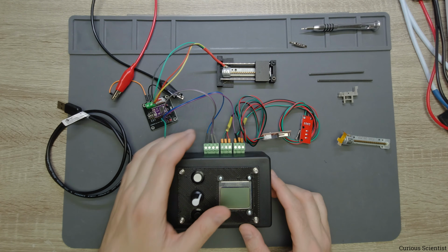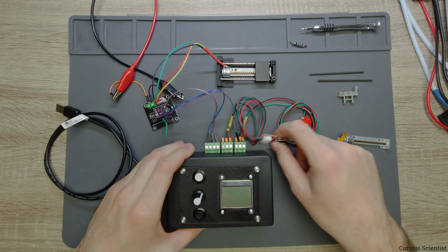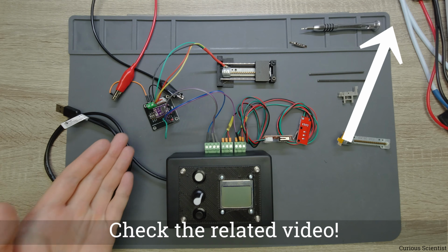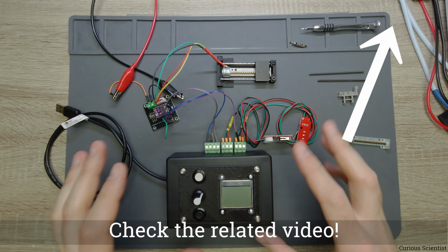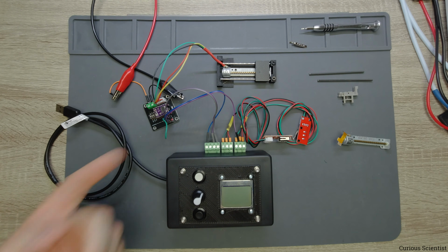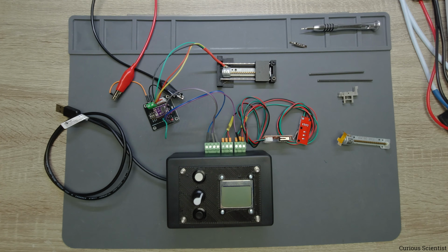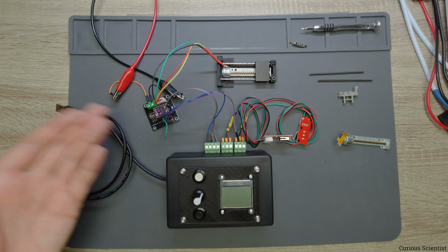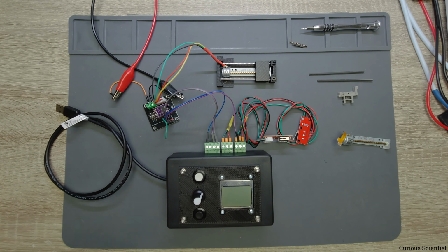And then the other output here on the left side, these four terminals, is for stepper motors. I have a video which you can see up here in the corner, where I showed that you can drive any kind of stepper motor driver with the same code and same environment, as long as it works with step and direction pins. In this case, I will run this system with a DRV8825 stepper motor driver, but in fact I could replace it with an Easy Driver or a TB6600 and so on, because they can all work with step and direction pins.